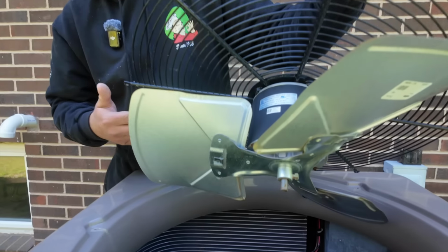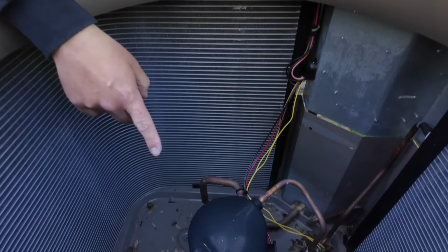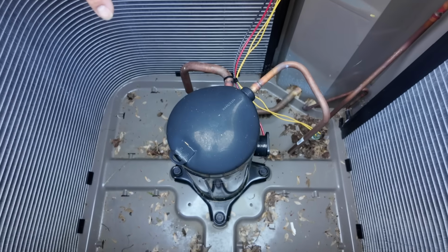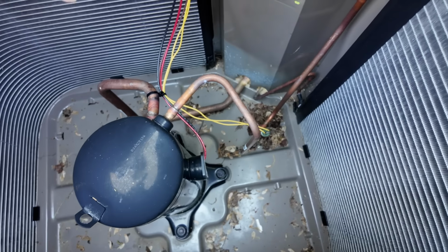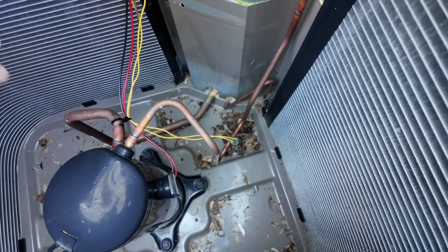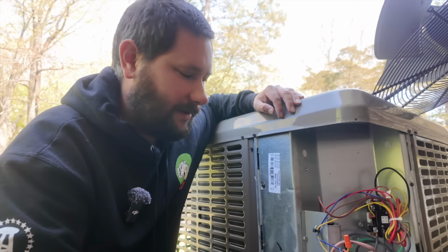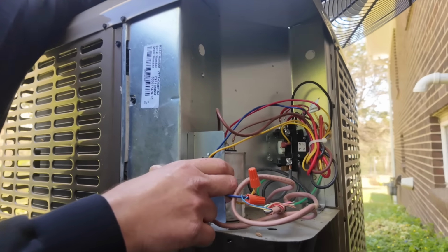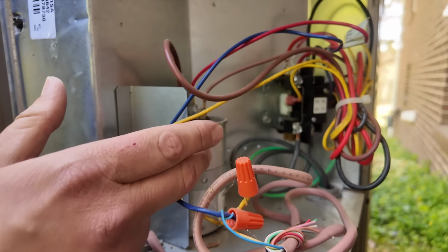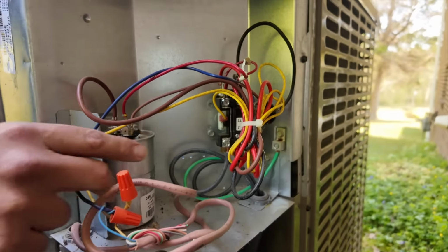First, we're going to learn how to read schematics for this air conditioner. What components does an air conditioner have? Outdoor fan motor. Looks like we got a compressor. And then there's some wiring going to something on the copper over there. Looks like some type of sensor or pressure switch. What other components do we have? We've got, in the electrical compartment, a dual capacitor and a contactor.